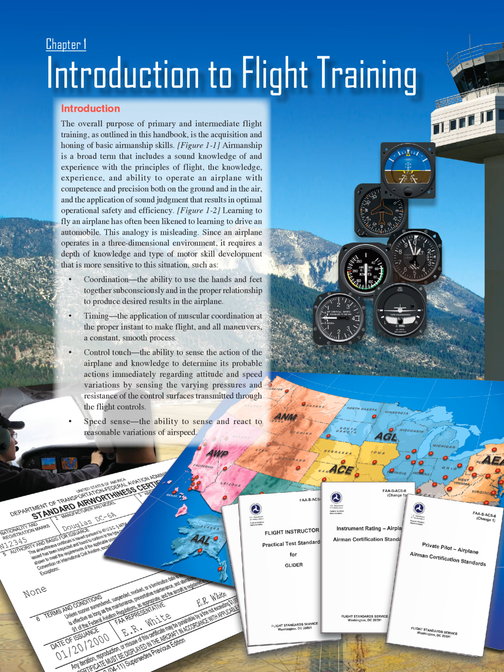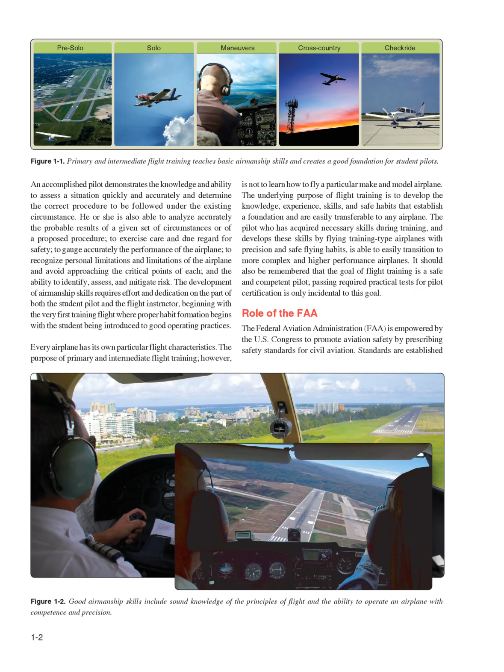Control touch, the ability to sense the action of the airplane and knowledge to determine its probable actions immediately regarding attitude and speed variations by sensing the varying pressures and resistance of the control surfaces transmitted through the flight controls. Speed sense, the ability to sense and react to reasonable variations of airspeed. An accomplished pilot demonstrates the knowledge and ability to assess a situation quickly and accurately and determine the correct procedure to be followed under the existing circumstance.